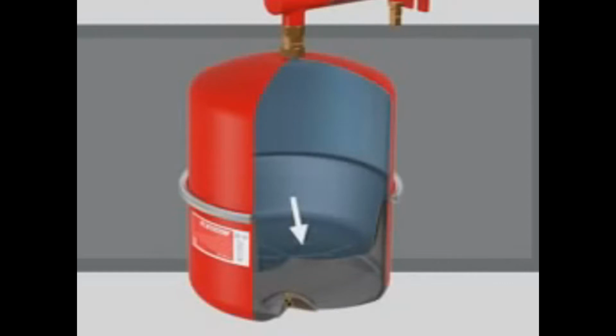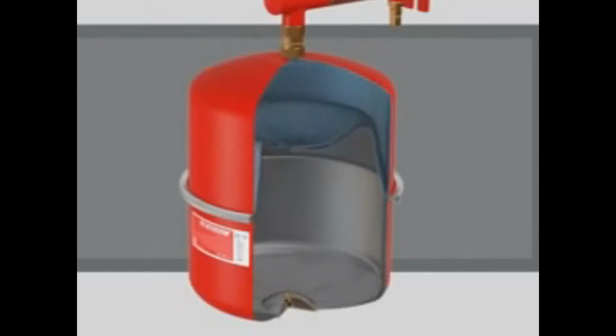The membrane fixed in the body, diaphragm type, has a range of expansion and movement that is not as great as in a bladder. When heated, the bladder is constantly moving inside the vessel. If the inner surface of the tank has sharp protrusions or roughness, then the membrane can be damaged and torn. It will need to be replaced. Although this process is not complicated, it takes some time.